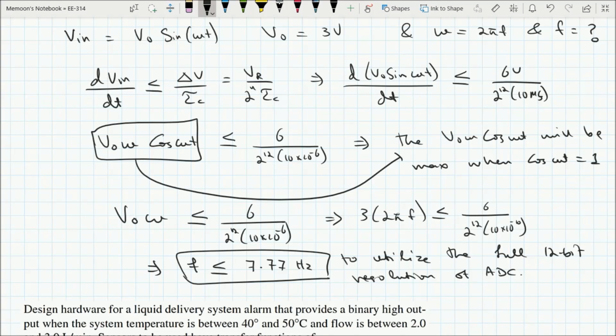So it happens many times that your ADC is not supporting your very quickly changing input signal from the sensor, and that input signal from the sensor is used as a feedback in a control loop, and your control system is behaving in an anomalous way, and you are not understanding why, because everything else seems fine, but you have not considered this limitation of frequency, the maximum frequency of the input voltage, and all the error is coming from the conversion from an analog signal to digital signal. So do keep these conversions in mind while designing your process control systems.